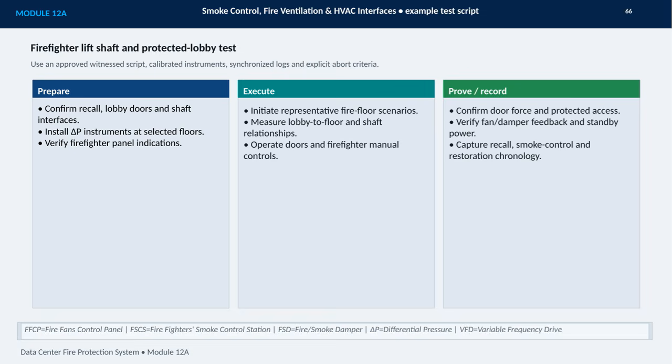The final stage is to prove performance and preserve the evidence. We confirm door force and protected access, verify fan and damper feedback along with standby power, and record the complete chronology from recall through smoke control operation and system restoration.